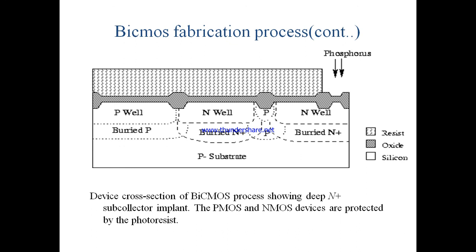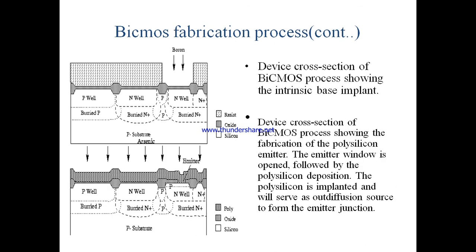A deep N plus subcollector implant is done while the PMOS and NMOS devices are protected by the photoresist. It shows the intrinsic base implant.